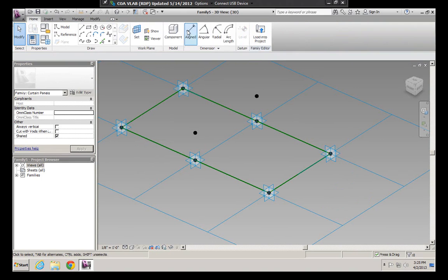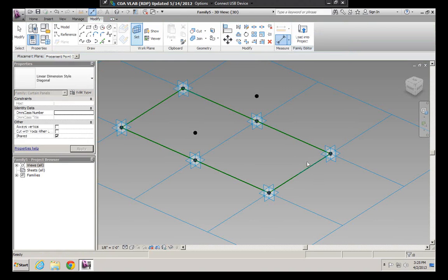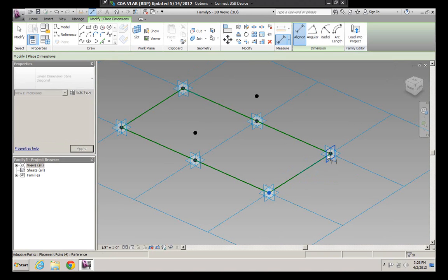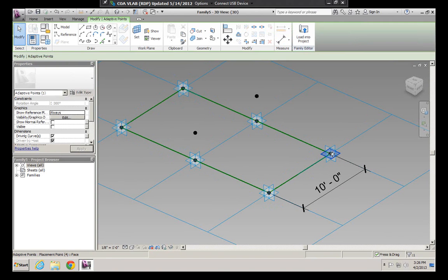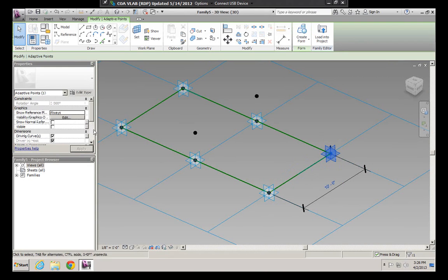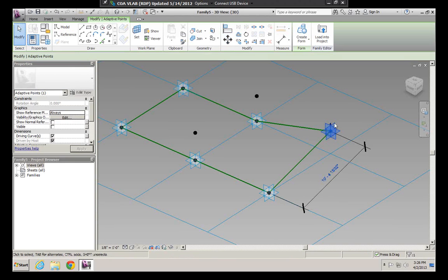When we do the angular aligned dimension, I need to specify the work plane. So I go to set work plane, and that work plane needs to be on this line. The dashed line is the plane. So these 2 points might not be aligned in 3D, so we need to get the aligned location regardless. So if I, for instance, let's try moving that point if we can. I don't think it's giving me the option. Actually, we can move it, yeah.